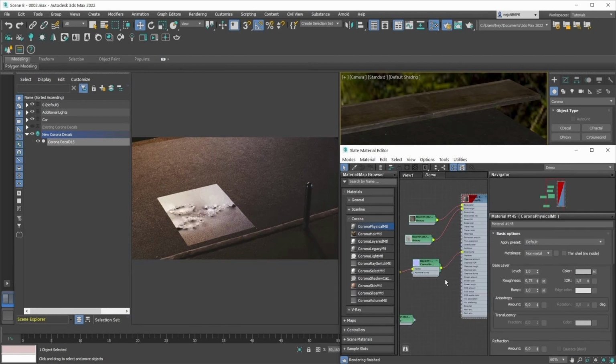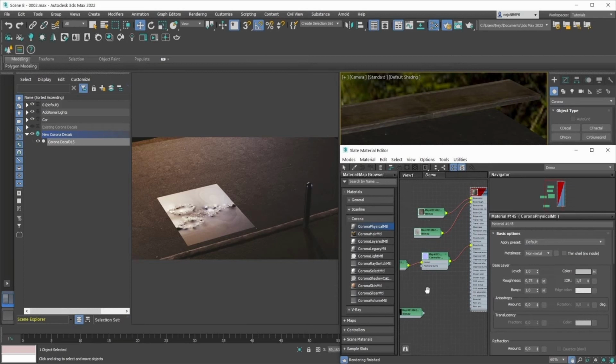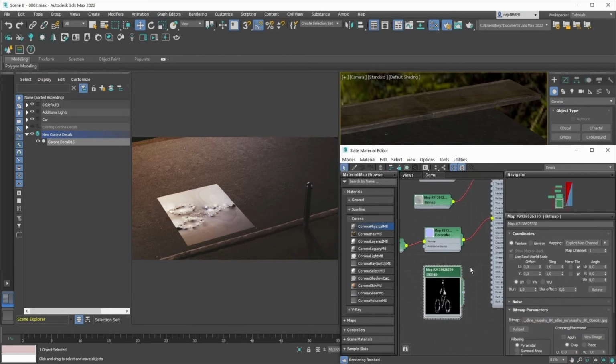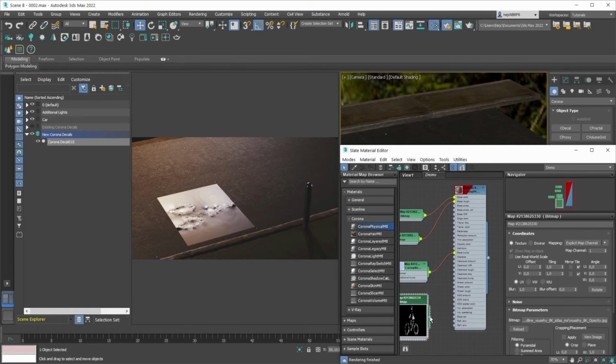And so now, as you can see in the interactive renderer, we're already kind of getting that shape we want. There's some detailing going on, but there's still that rectangle-ish blob happening. And that's not exactly what we want still, right? We don't want that rectangle there. We just want a bicycle lane marking. And to get that going, you also need an opacity map. It's just a simple opacity map of that bicycle lane marking. We're going to plug it into the opacity color slot.